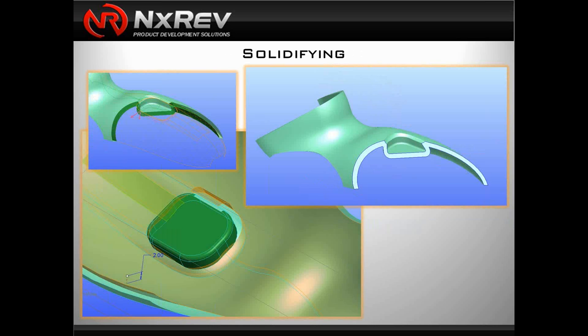And the last one was solidifying. We took the geometry or surfaces that were failing when we were actually solidifying the model and did the offsets in 2 stages, not a single stage. Once we did that, we were able to piece everything back together using the merge tool. Once that was all merged back together, we simply grabbed the single surface quilt and we're able to solidify them.